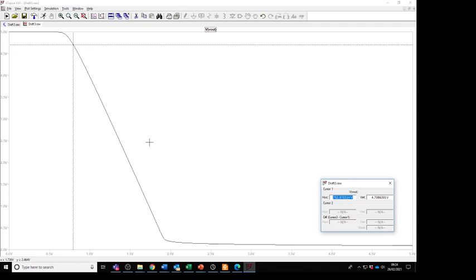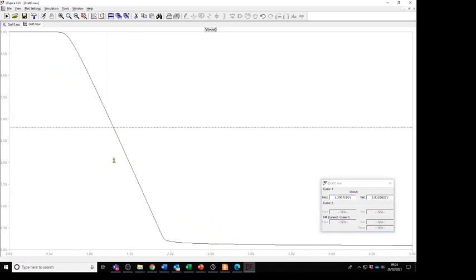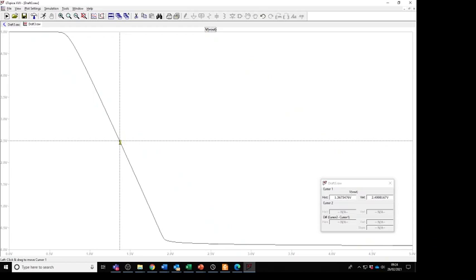Right, so now we can start to look at our circuit and ask how we work out what's going on in it. We would like to be operating at this point here, at 2.5 volts, as a bias condition with no signal going in. Then when an input signal comes in, it moves around this point, gets amplified, and comes out of here. The simulator will allow us to dig into that a little more as well.